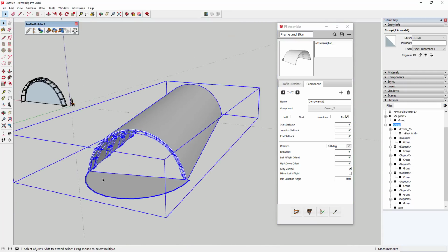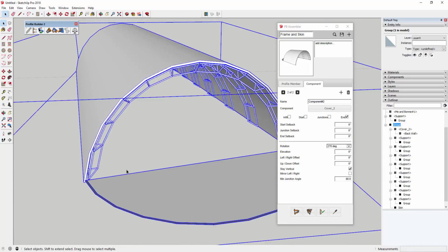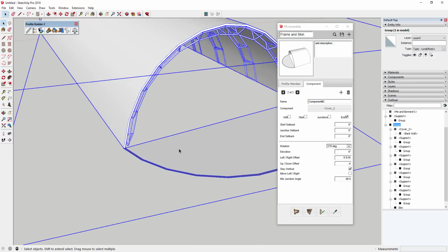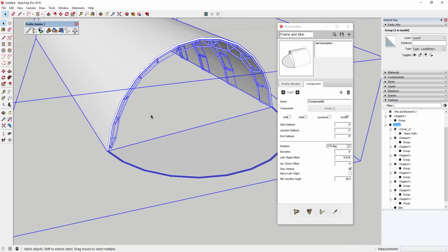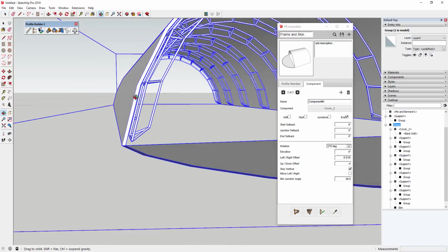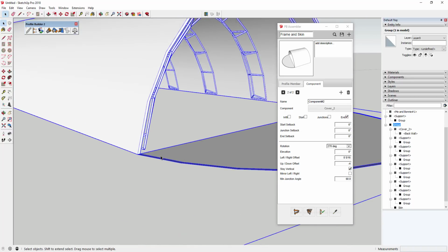So you can see how when I select that 270-degree rotation, that rotates this so it sits on this back wall. Alright, so basically what you're going to have to do is set your left-right offsets. I had done some scaling in here that I probably shouldn't have done, so that made everything not match up quite right. But basically all you have to do is set up your left-right offsets and also your up-down offsets so this all matches what you're trying to set up.